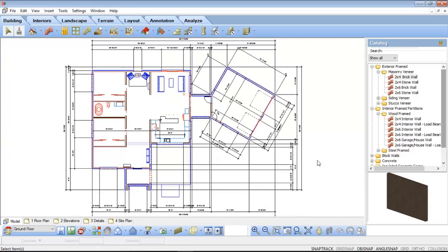So again, here in Model Space, you can see you have a number of automatic and manual dimensioning tools that are very handy for annotating your floor plans before you go and take them and place them into worksheet space. We also have some text tools available to us here in model space that we might want to take advantage of before we go and insert this into a worksheet.